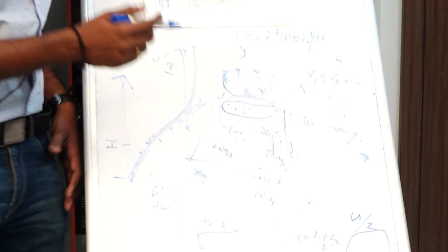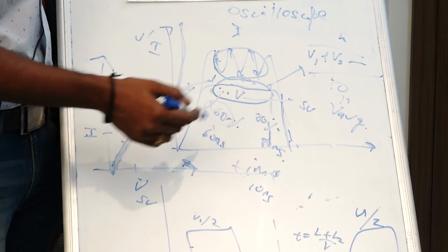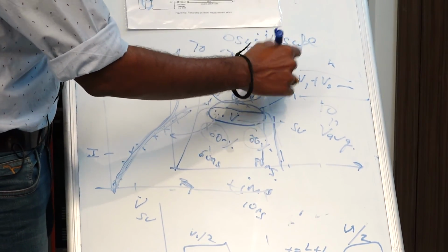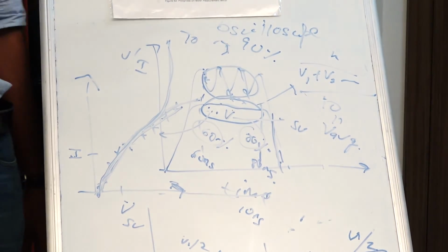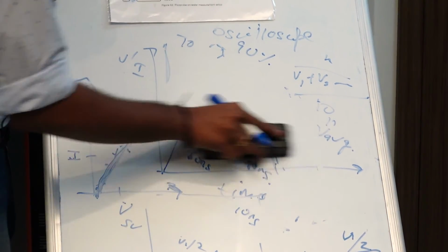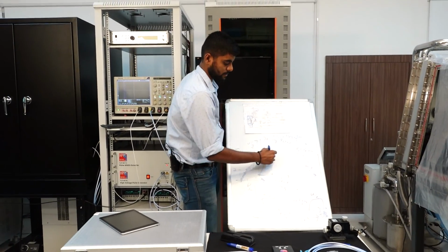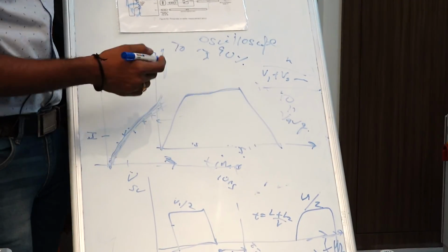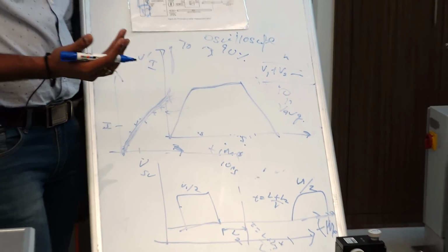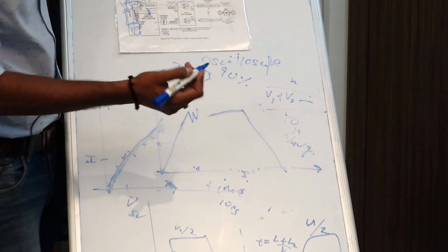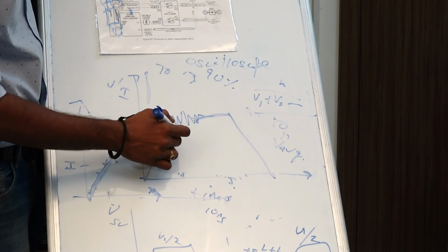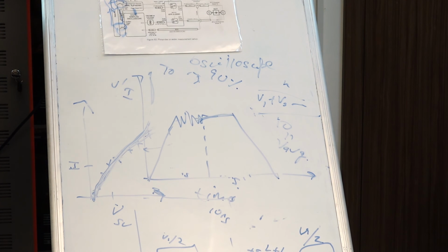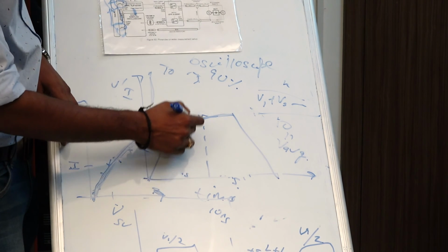Now one thing to notice is that when I was talking about averaging, I talked about averaging in the latter half of the voltage waveform, 60 to 80%, 70 to 90%, whatever you like. Why did I do that? The voltage waveforms that we are talking about are rectangular in nature. While I am showing you this as a straight line, a perfectly balanced signal, it may not be so. It may have some ringing here and there. When you apply a very high voltage pulse to anything, you would have some overshoots as well, and some undershoots.